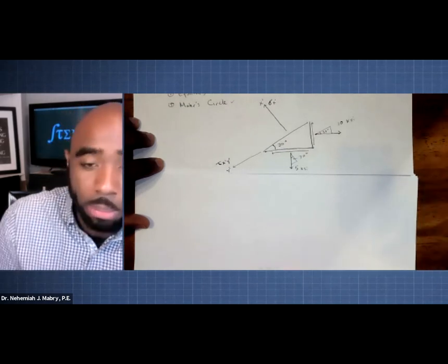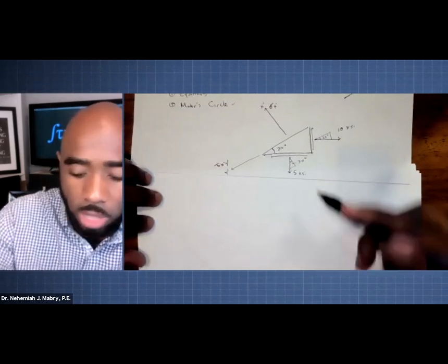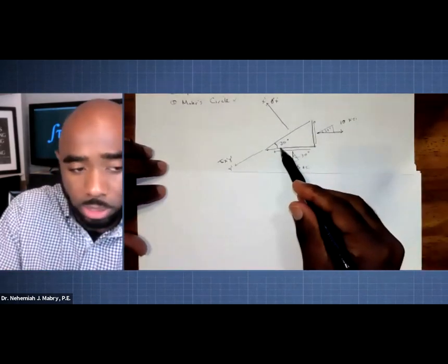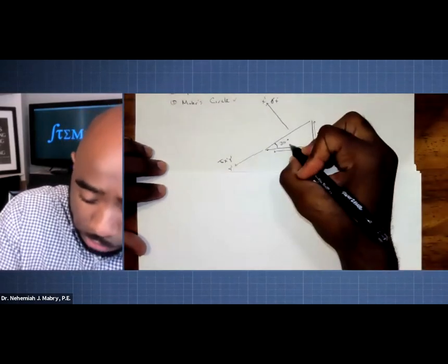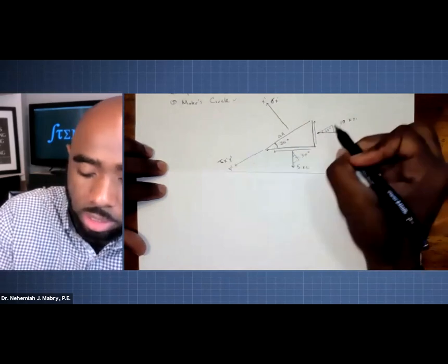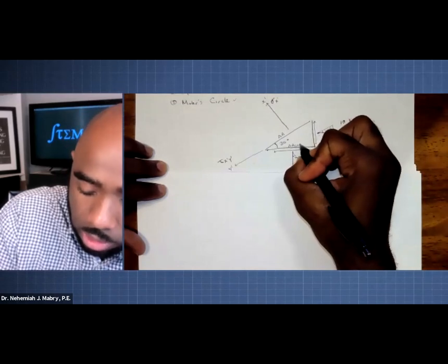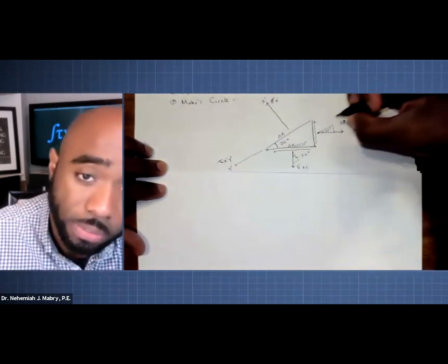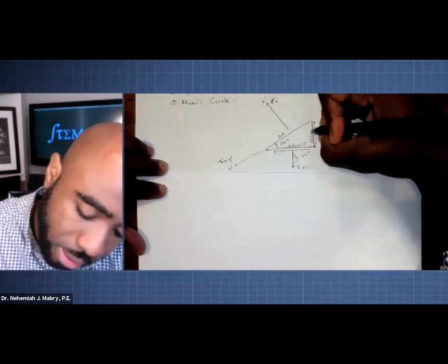All right. Let me keep explaining this. If you want to continue, if you want to revisit it, let me know. But my suggestion would be to focus on solving these with the equilibrium method. To go back where I was in the problem, this bottom side is going to be found. If this face is delta A, the hypotenuse is delta A. This space right here is delta A cosine 30. And then this face here is delta A sine 30.